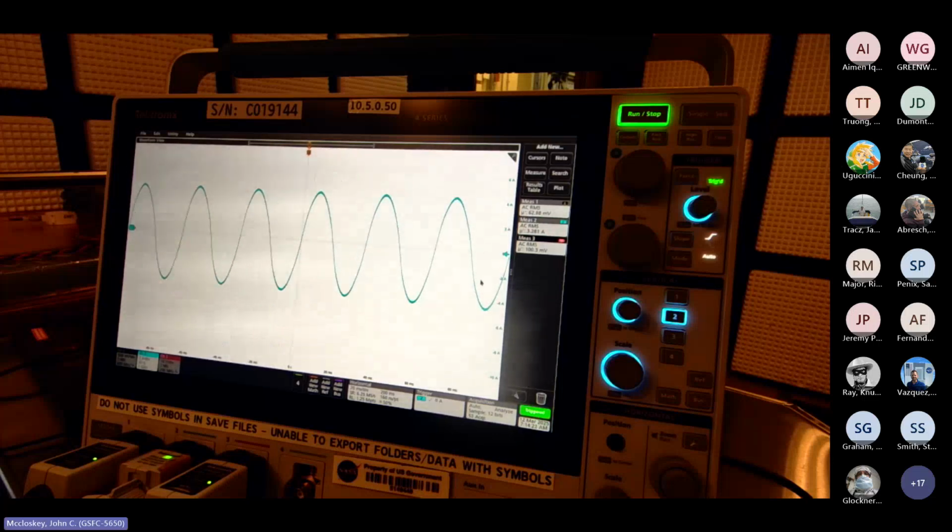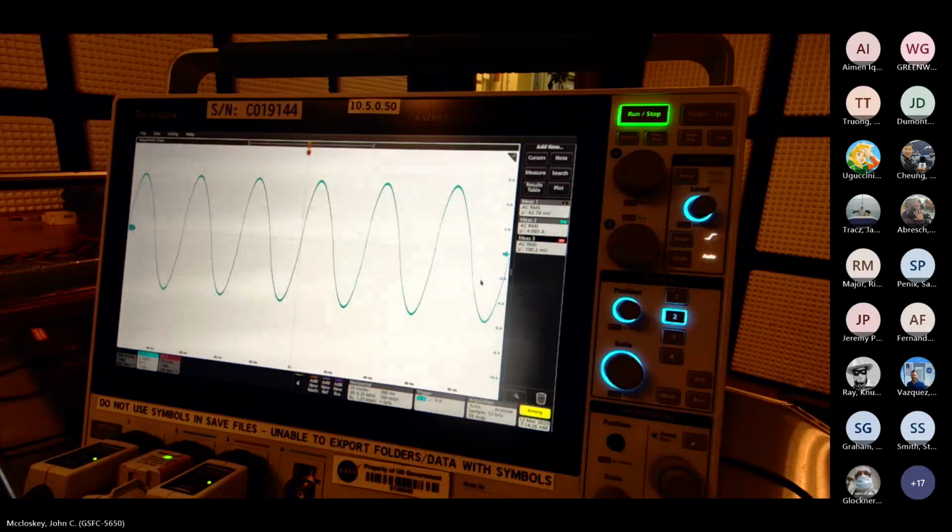So we were at minus 9.7. All right, so now at 30 hertz, minus 9.7 dBm, we are getting just over 4 amps. All right, 4.074 amps. If we just call that 4 amps, that's what we would expect for our advertised 2 ohm source impedance of our drive amplifier going through our 2-to-1 step down transformer. It's going to step it down to half an ohm, so you have half ohm source impedance going into a half ohm load.